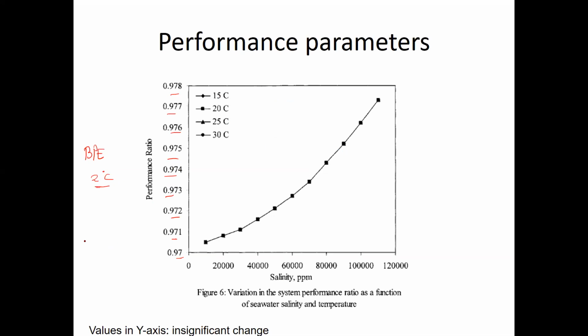So the seawater, as it is being admitted before it enters the evaporator, has to have a pre-treatment so that we add chemicals into it to take care of the issue of salt precipitation (ترسب الأملاح) on the surface of the tubes. And this is a standard process for any desalination system that we have.